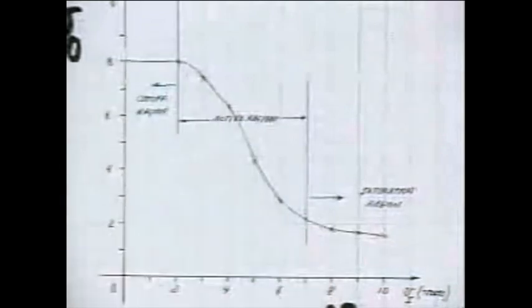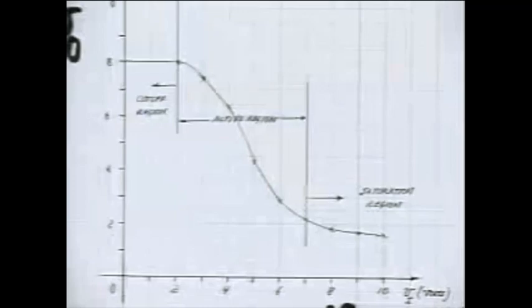In the active region, the device can be thought of as an amplifier. How can we describe the voltage gain of the amplifier, under some limited conditions within the active region? Well, the incremental or small signal gain is related to the slope of this transfer characteristic. And at this point, I'm differentiating between total variables, V sub capital O and V sub capital I, and incremental or small signal variables. In other words, what I'm going to do is pick an operating point somewhere in this active region.